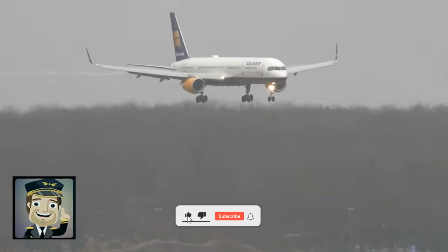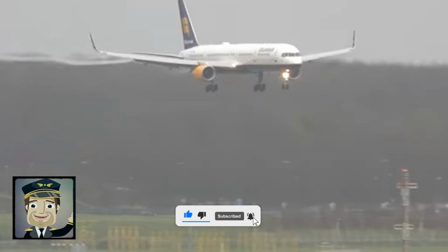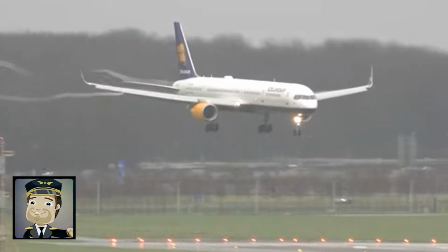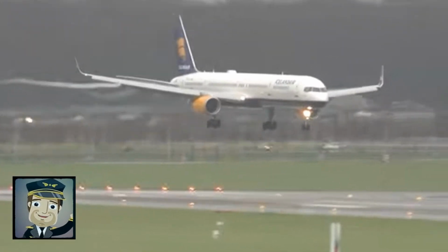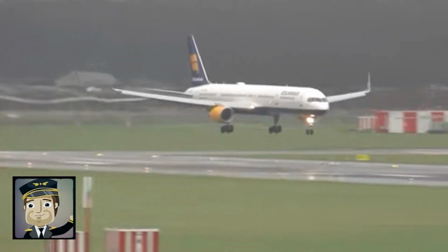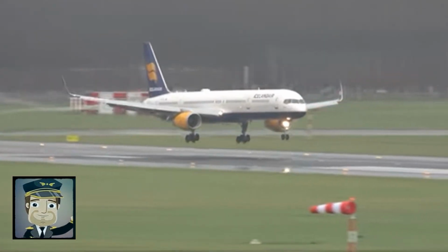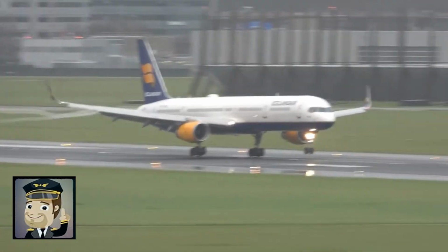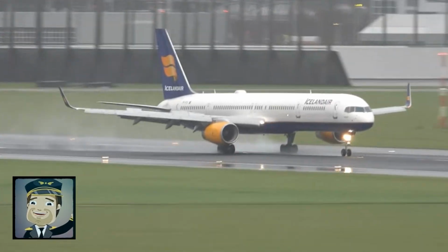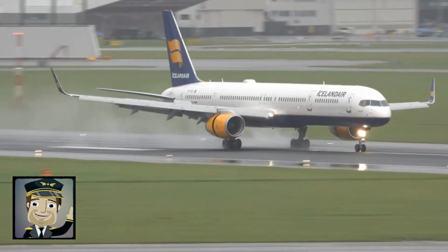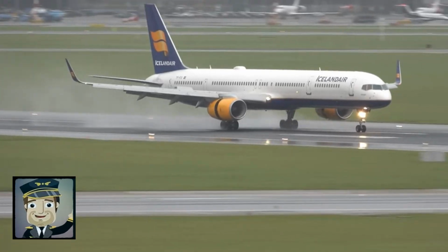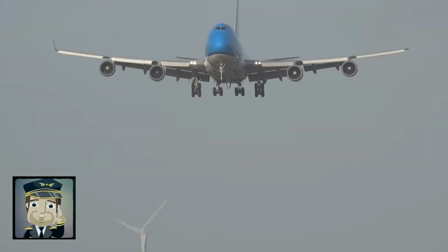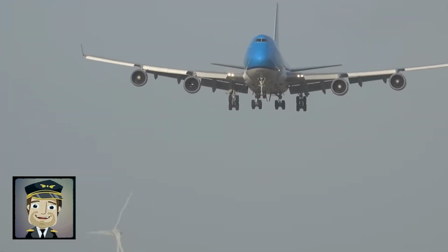and coordination is essential. A crosswind occurs whenever the wind component is not fully aligned with the runway. It may come from different angles, from front or behind, but it is a lateral component that creates the greatest difficulty. Pilots use information from onboard instruments, such as the wind indicator in the cockpit, and from control towers, which provide real-time data on wind direction and intensity. These data are fundamental for the captain to decide which technique to apply, since the way of executing the landing depends directly on the crosswind strength and the aircraft's characteristics.